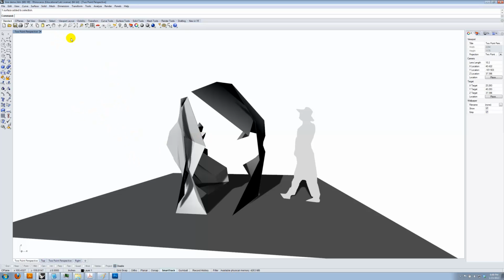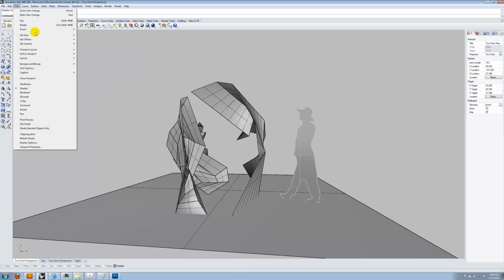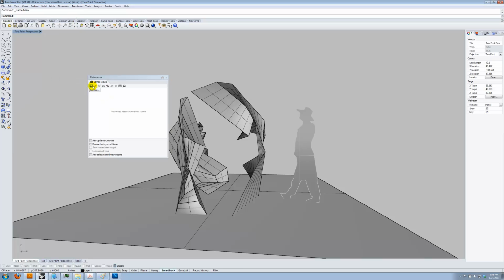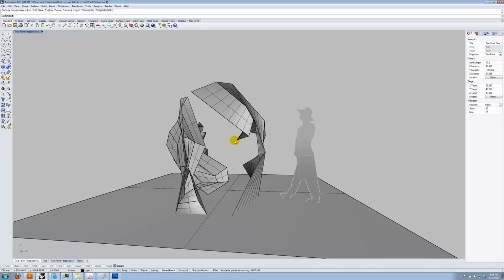But anyway, once you've got that, you can go ahead and do your Make 2D. I'm sorry. What you want to do is actually first save your view. So go to Set View, Named Views, and save that view, and you can call it 2-point perspective 1. This way, if I close this, you can always get back to it. I have different views, like top, bottom, left, right. You can always go back to 2-point perspective, and you get exactly this view at this zoom. That's important if you open the file up later and you want to export lines. You didn't lose your view.